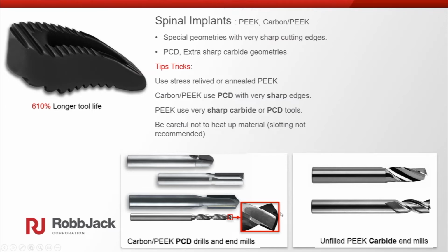So all the cutting edges are PCD, but new technology has allowed us, instead of the old days of having just a flat sheet of diamond on there that kind of slapped off the material, we're able to have all that full rake and relief and angles that you would have on a solid carbide tool on diamond. So we're able to get better finishes, sharper edges for the medical parts, and able to really improve performance, speeds and feeds, and get the life with PCD in those types of applications.